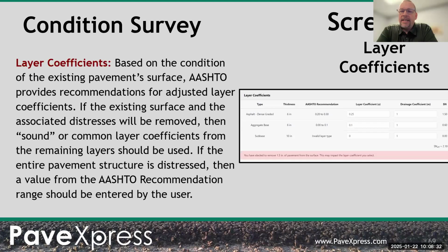You'd probably just put that in as your subgrade, because you're not removing it. If your subgrade is actually all sand, then that's going to affect the resilient modulus of your subgrade. Instead of 5,000 or 10,000, it might be 20,000, so you can bump that up. The nice thing about this program is that you can do a couple of iterations and see: does putting in a thickness here change anything? Does adjusting that modulus change anything drastically?